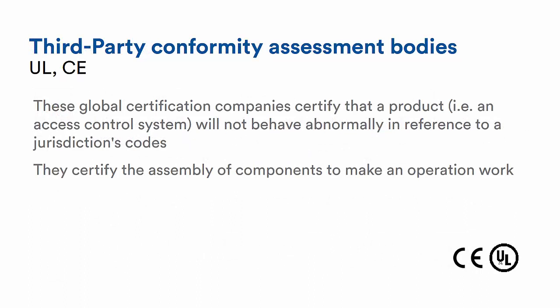This is where certification companies come into the mix, like Underwriters Laboratories, or UL, and CE, which stands for Conformité Européenne, which literally means European conformity. Now, if a product carries this mark, Underwriters Laboratories and CE found that samples of this product met their respective safety requirements. In the case of UL, these requirements are primarily based on their own published standards for safety.